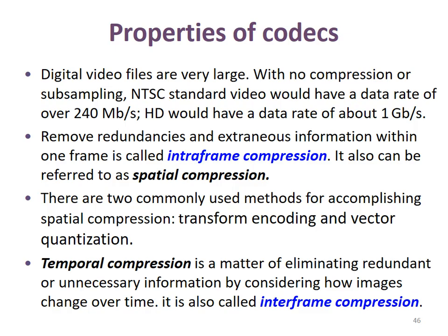And for inter-frame compression, we know video is a sequence of images along a time interval. So we can compare the redundancy of neighboring frames. If we have the complete content of the first frame, then this one is very similar to the second frame. So maybe we can compress the second frame based on the analysis of inter-frame relationships. So this could be compressed more than the first one.